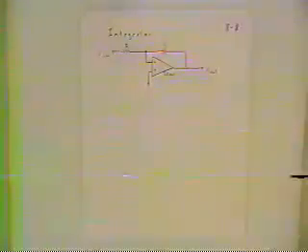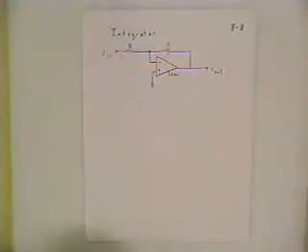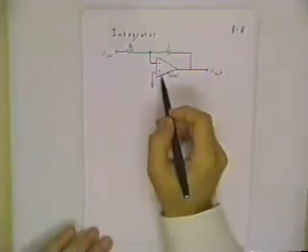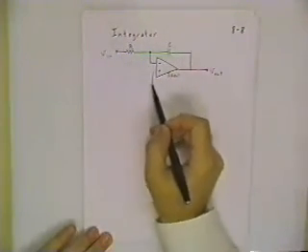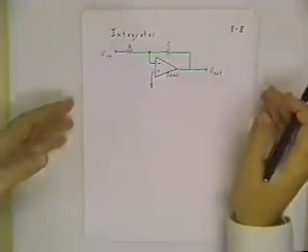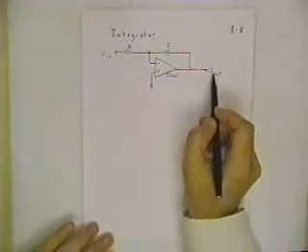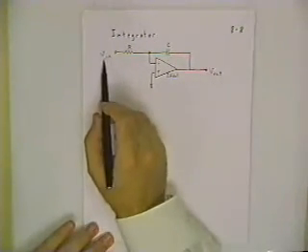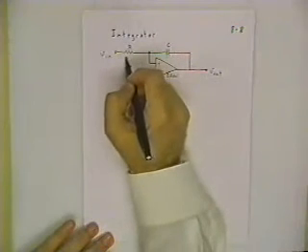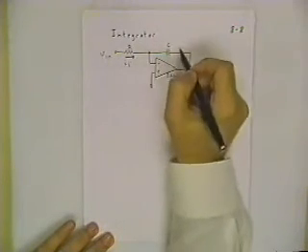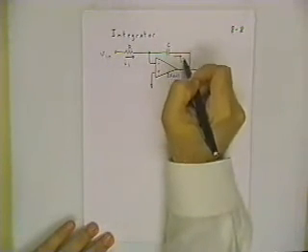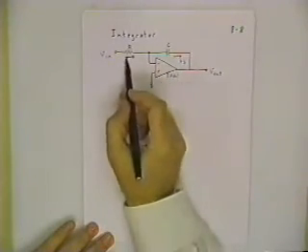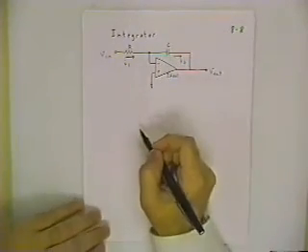Well, as one last example, let me show you the op-amp integrator and where it comes from. Notice that I'm using the same basic layout as for the inverting amplifier. So one thing that we can expect is probably the output is going to be inverted with respect to the input. But the way we're going to decipher this problem is, again, just using the linear model for the capacitor and the ideal model for the op-amp.